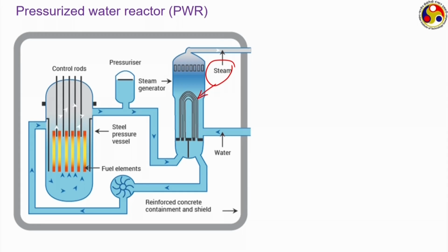So, the moderator and the coolant and also the water in the outside circuit are all water from a chemical point of view, but the water which is used as the moderator inside the reactor is not the working medium. Rather, the working medium will be water, but some other body of water or some separate quantity of water which circulates only in the external circuit. So, a pressurized water reactor employs water as moderator, coolant and also working substance, but the working fluid remains separated from the moderator.